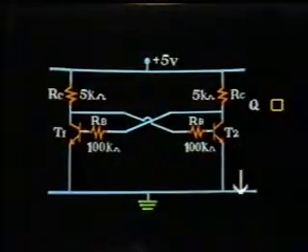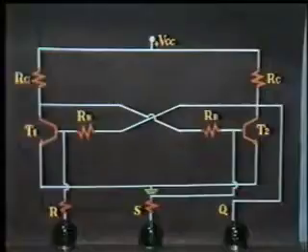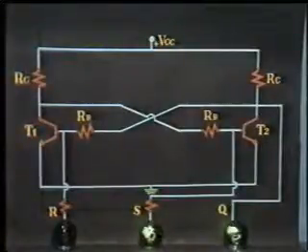In this latch circuit, we now introduce two control inputs, the R or reset input and the S or set input. A bulb glowing on any line indicates that that line is at logic level 1. A positive trigger at S input only makes Q equal to 1. This is set state. R equal to 0, S equal to 1 makes Q equal to 1.